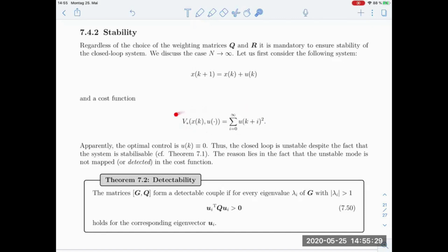However, if we are only interested in the cost function u squared, then, as we've seen before, in our limit, the open loop eigenvalue would just be mirrored. Now, this is already the stability limit, and essentially, it will stay there. We will not improve the situation. We will just get a non-active controller. The controller will just be u of k equals 0, which is not really useful. So in that sense, we failed to impart asymptotic stability to the plant.